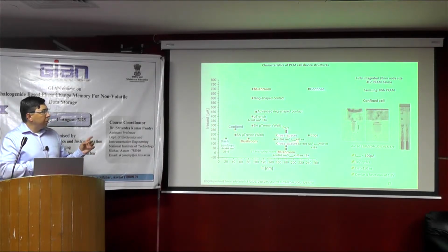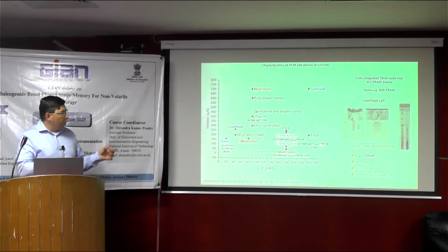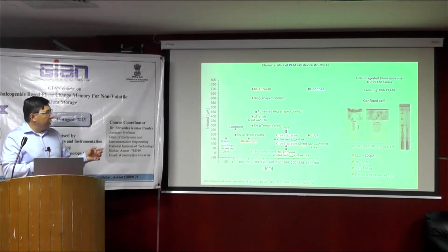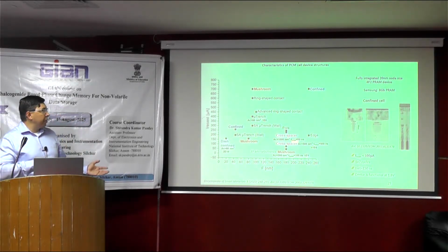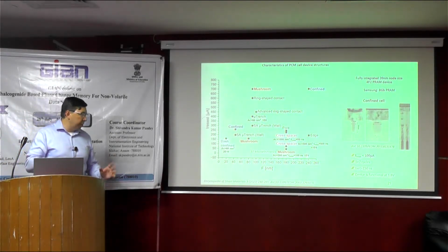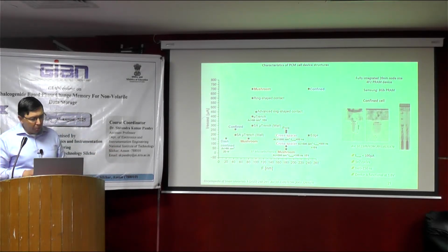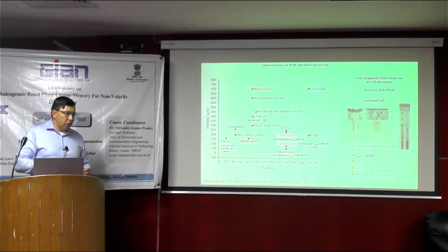If you use a longer pulse and a little bit larger area or smaller area, you can get a little bit smaller reset current. So different technology, but the results are the same. So if you make the line here, we can get this 200 microamps with different technology, and by using different schemes of switching, as mentioned by Shivendra in the talk before.